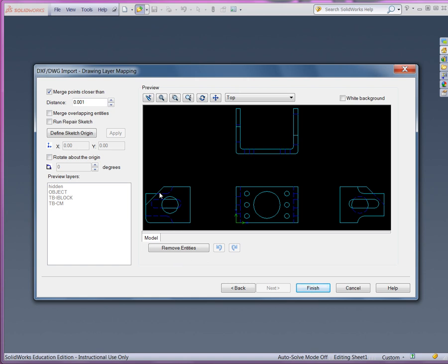But if you're not sure, you can change the tolerance here to make sure that if anything is less than what's shown there, a gap can be closed. We don't have to worry about this because we know that we used Object Snap modes. Okay, so all profiles are closed. Alright, once we do that, we can finish.